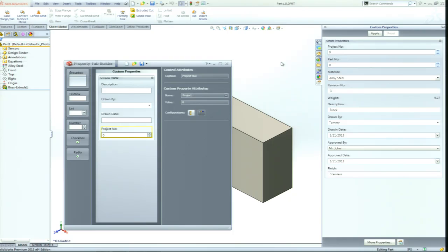So in other words, if you create a part and you have 10 different configurations, you don't have to have all 10 sheets of those configurations in one file with the drawing. You can now paste those drawings apart and keep them separate. And you only have to do one. You don't have to do multiple drawings, so you do the one drawing. Any questions, guys?